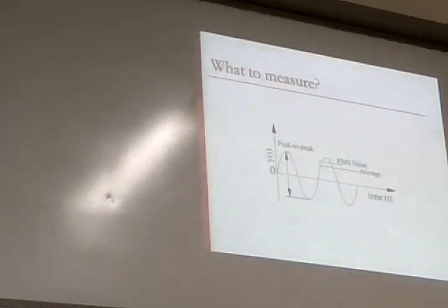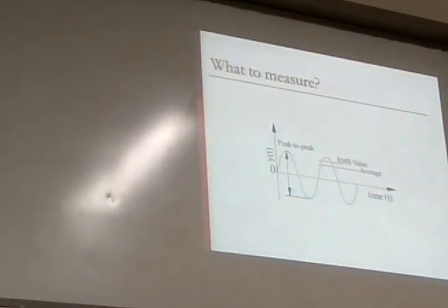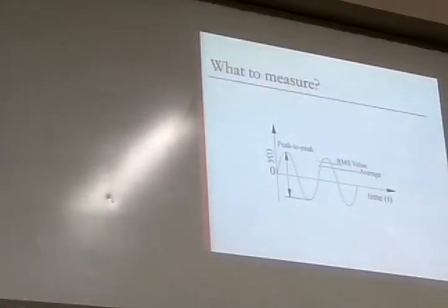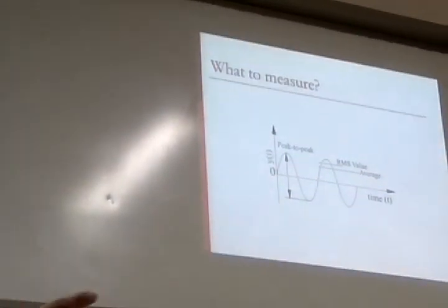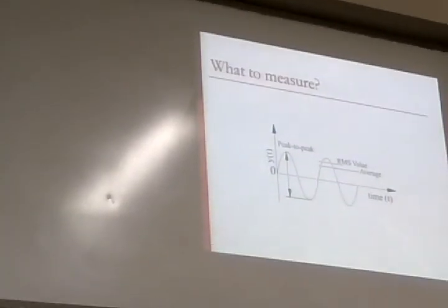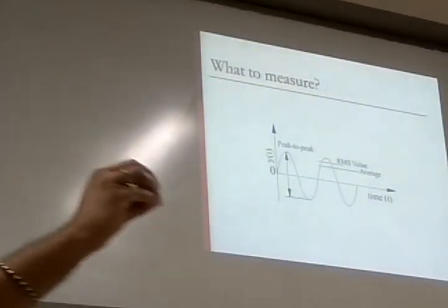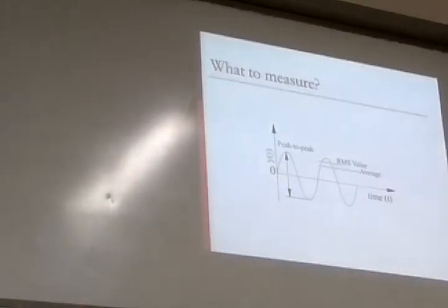Okay. So, vibration is not a static parameter. It does not have a single value for a given measurement of time. When you take a measurement at a particular time, it does not have a single value. It is a time varying parameter. Okay. But when we want to assign one number to that given vibration condition, then you have to compute some parameter and then say this is the vibration level. For that, we commonly use these three parameters. Up to this is clear? Yes, we have not gone into measurement at all. We are just learning the fundamentals.